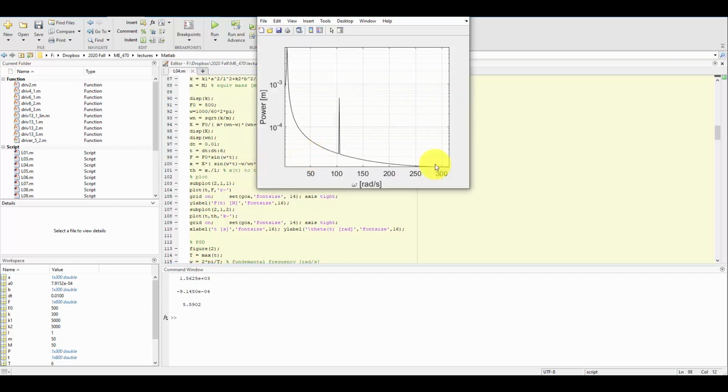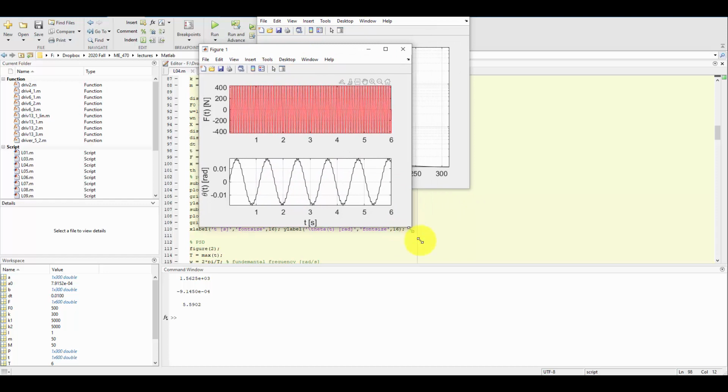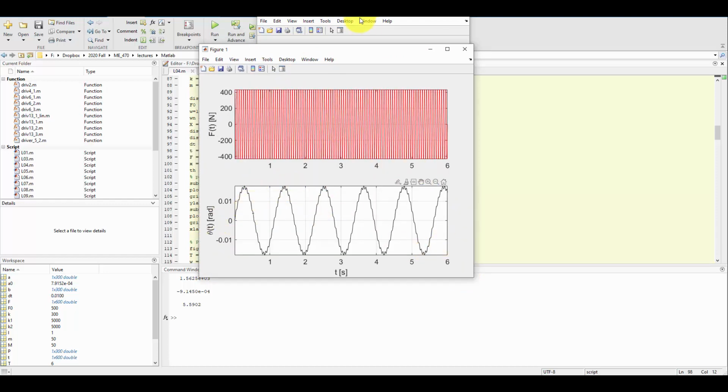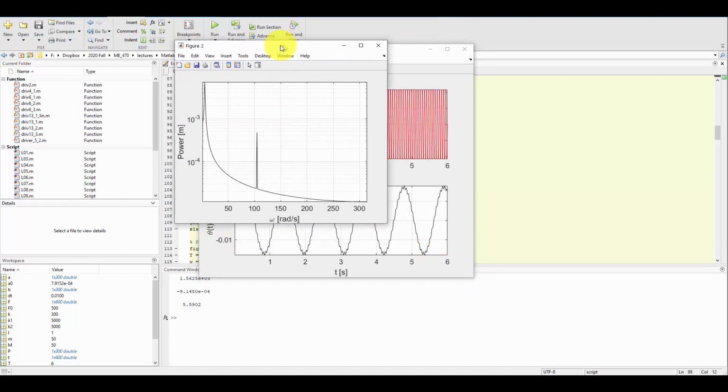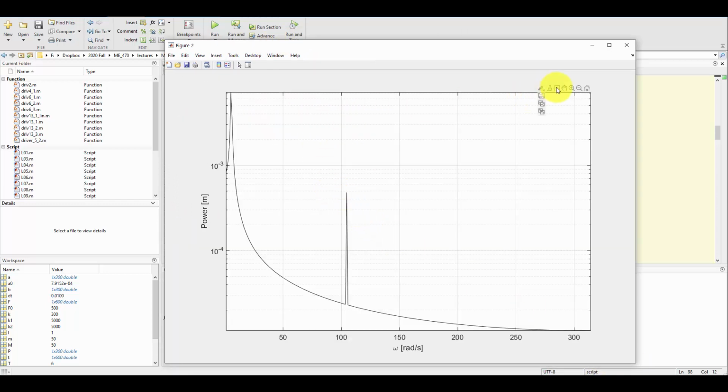So we've sampled longer, and that's reflected here in the plot. We have more oscillations because we sampled longer, and we see the power spectral density here. We have a much sharper peak because our resolution is better. So let's see, by tripling how long we sampled, where we're getting. So we're at 104.7. That's closer than we were before to the 105, and the 105 itself is slightly rounded. And our first peak we're seeing at 5.23. Again, that also seems closer to the 5.6 that we expect.